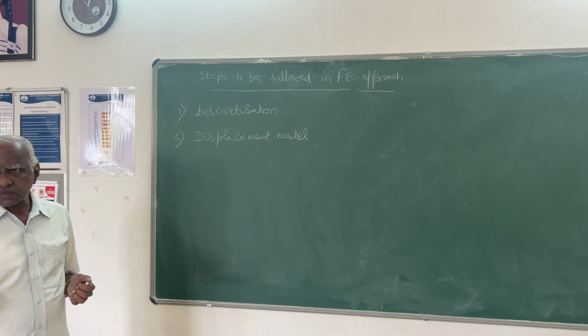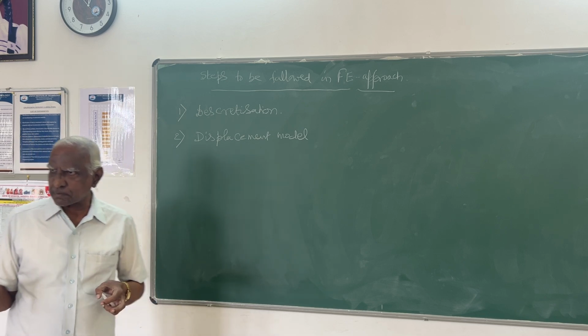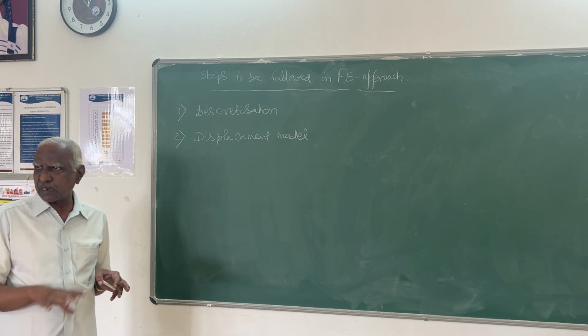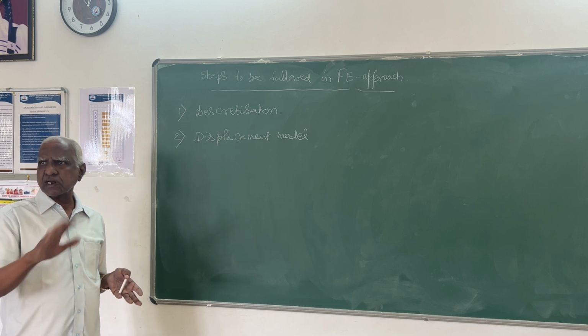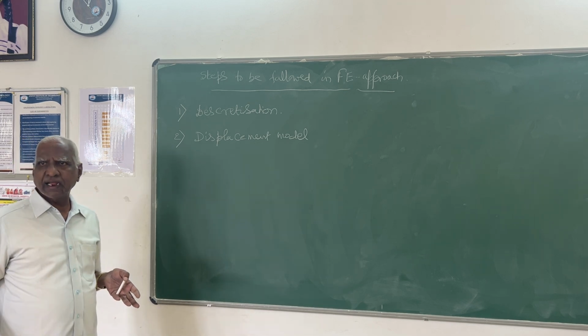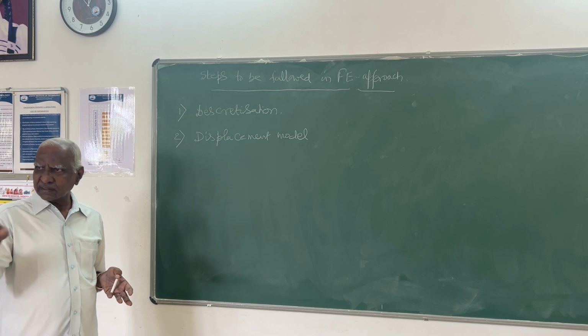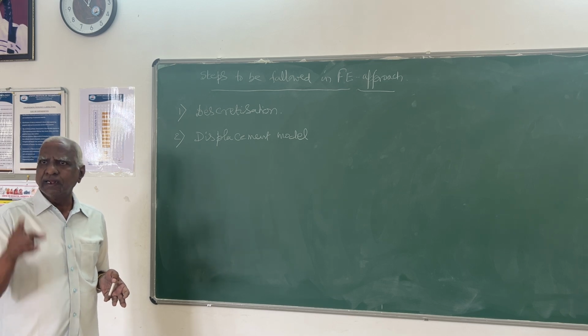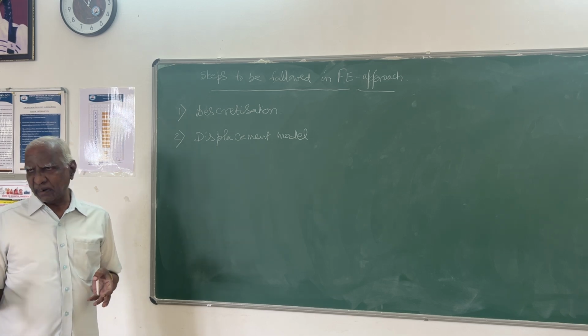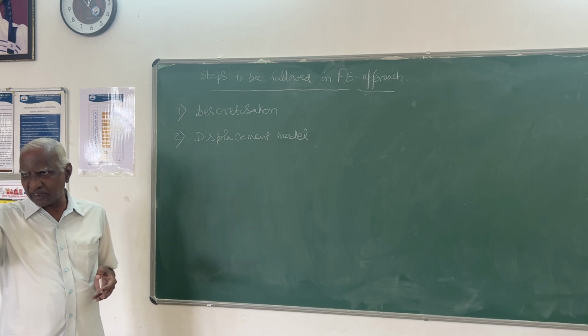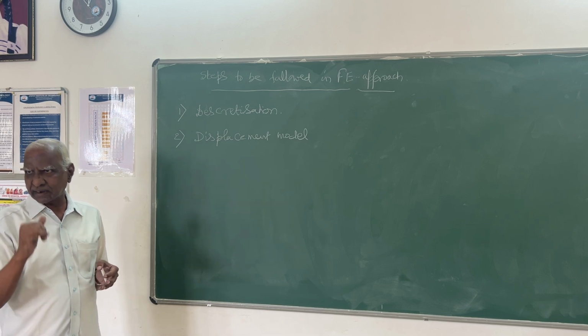Of course, angular displacement is not an independent displacement, it is a function of linear displacement. It is the first derivative of the linear displacement. Theta is nothing but dv by dx or dy by dx, where y or v is the translatory displacement.